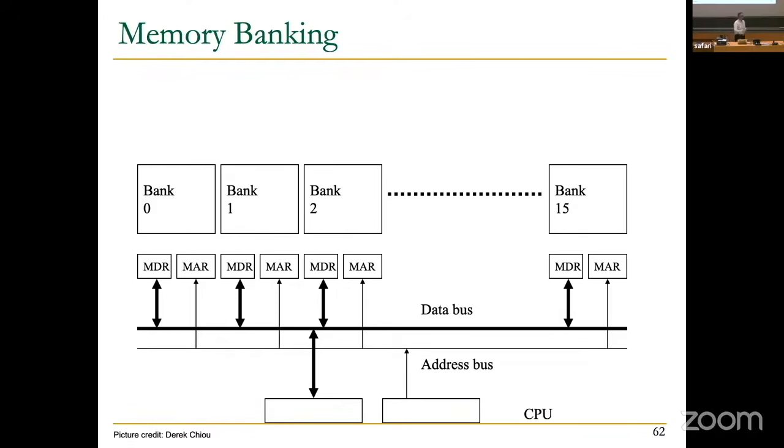That way we can start the operation or the memory access of a bank in the first cycle. And then if we need data from the next bank, we can start the memory access from that bank in the next cycle. So we can actually start memory accesses, one memory access per cycle from different banks. And if each bank takes 11 cycles, you just need 11 banks, right? But of course, 11 is not a great number to distribute your addresses to, because our addresses are fundamentally powers of 2. So that's why I have 16 over here.